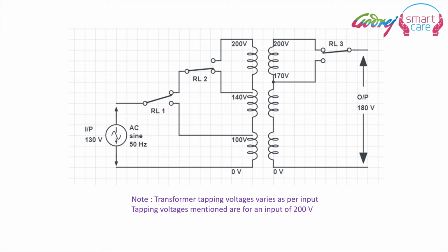In the second scenario, the input voltage is 130 volts, but at 130 volts the refrigerator won't work, so you have to step up the voltage to somewhere as high as 180 volts, and this is also done through switching of various relays and by connection of a different set of step up transformer windings to the circuit. All this is done through the comparator, which switches the relays in the switching card and gives the desired output voltage.